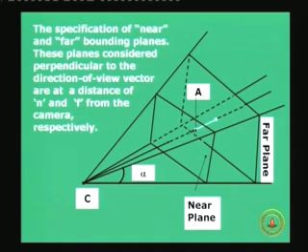And if you look into the figure again, in addition, of course, you will have 2 more surfaces. One is called a near plane and a far plane, or also called the front clipping plane and the back clipping plane. You have already known about FP and BP, front clipping plane and back clipping plane, with respect to those 6 surfaces where you are clipping your 3D points and surfaces and lines.